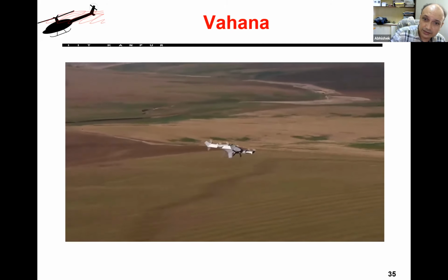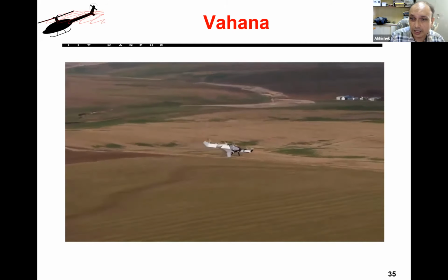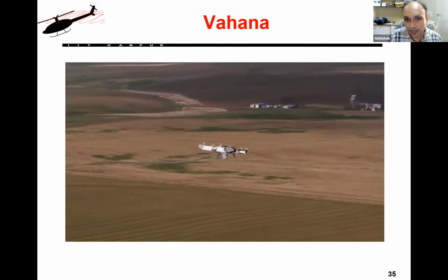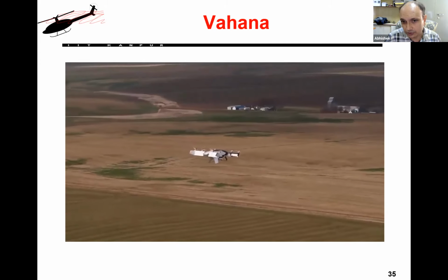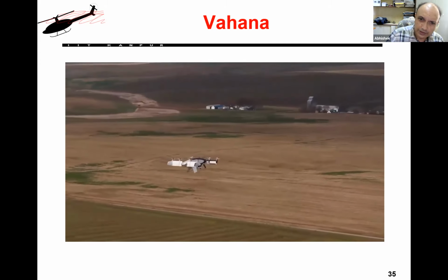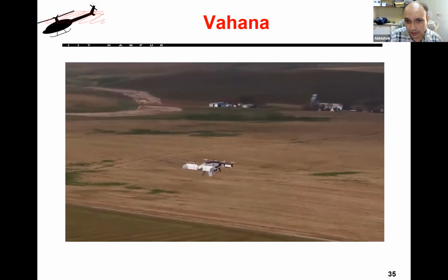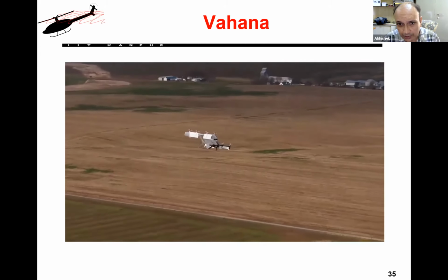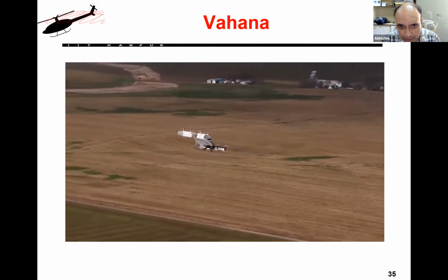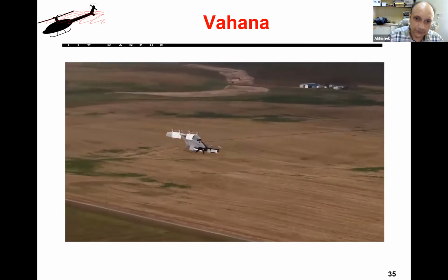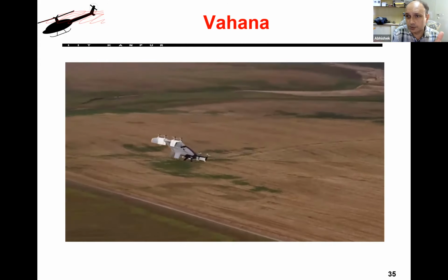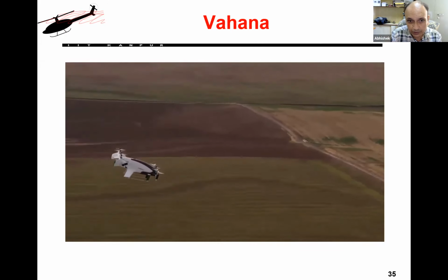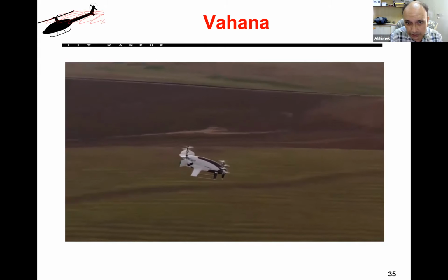So you can imagine this particular aerial vehicle has an extremely large number of control surfaces or control inputs. So you have RPM of 8 rotors, which you can control. You have pitch of these 8 propellers, which you can control. So you have 16. You have 4 sets of, I think there are some ailerons also. Or if not ailerons, I have the option to tilt the control, change the amount of tilt that is required. So by that logic, you have another 2 sets of inputs.